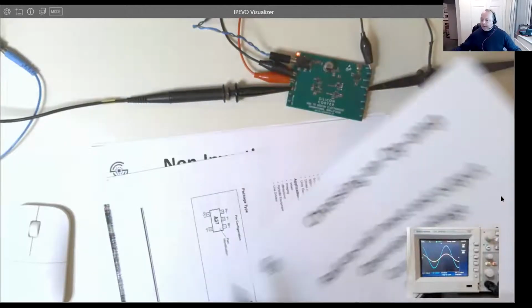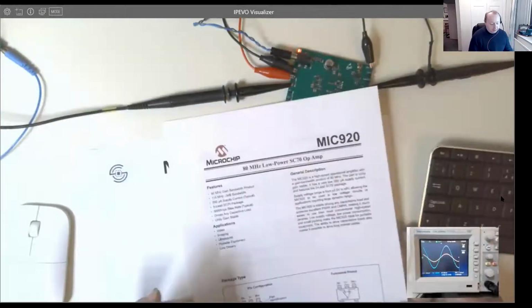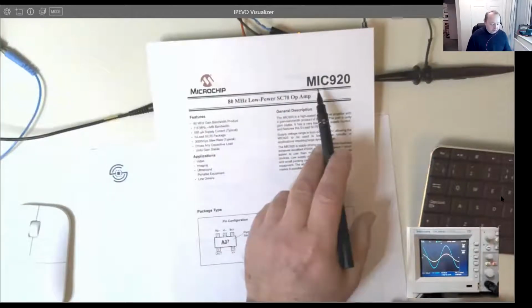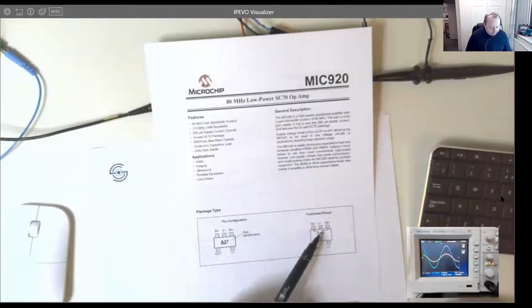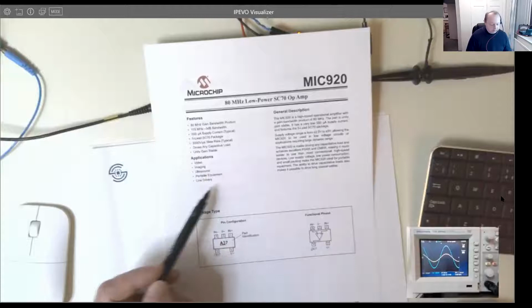So when I'm looking, if you look on DigiKey or any of these others, you can find data. These are just some examples of some data sheets, which this is the one we're using this evening from Microchip. It's got our positive rail V plus, our minus voltage here for our negative voltage. We've got 2 inputs. We'll look at them in a second. And of course, it's got an output. And that's pretty standard. And they always tell you various applications that they're good for.